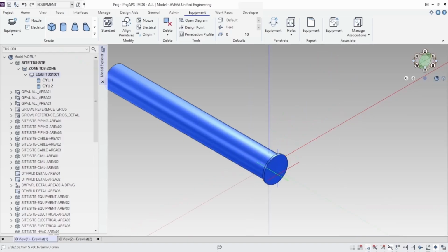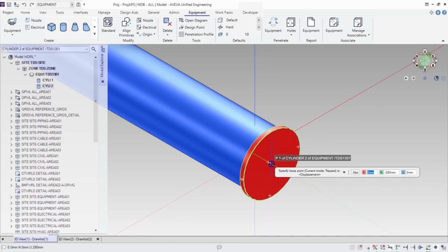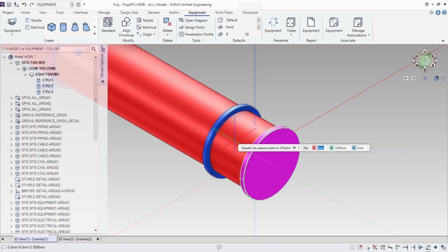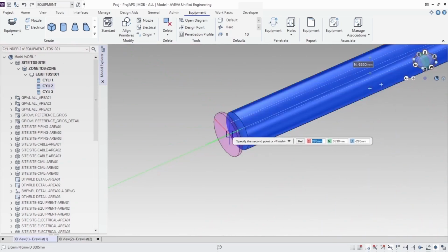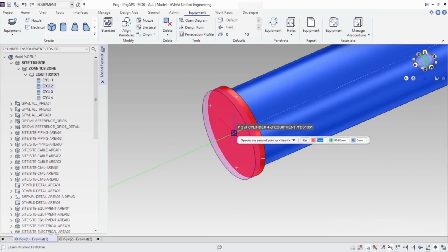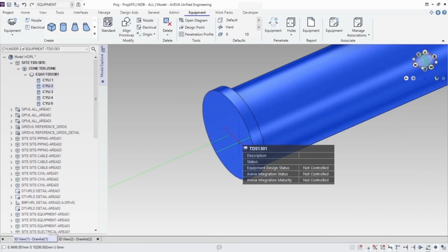Once that's done, we'll create additional copies. With the first cylinder selected, we enter the copy command in the view. We choose a base point on the original cylinder, and then place 3 copies. One 640 mm away, another at the opposite end, and a third placed right next to it. This gives us 3 new cylinders in addition to the original, forming the plates we need.